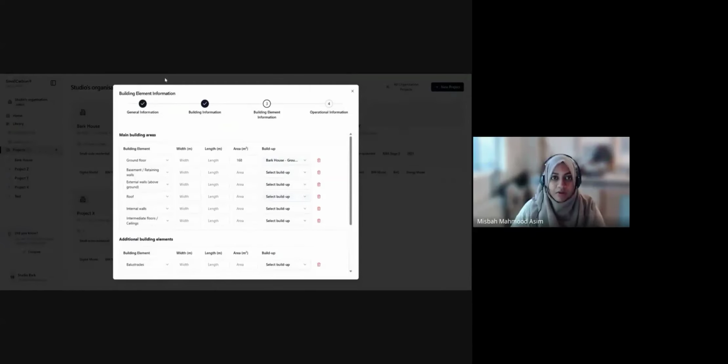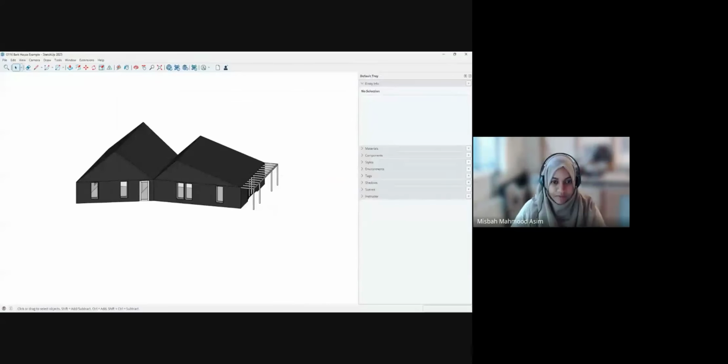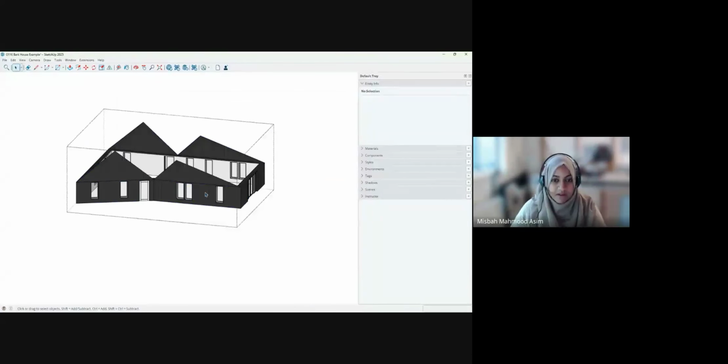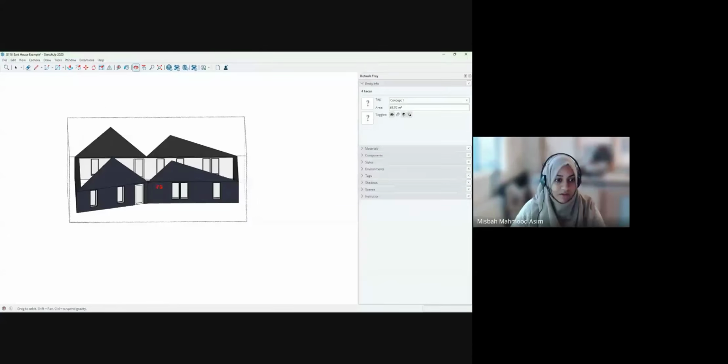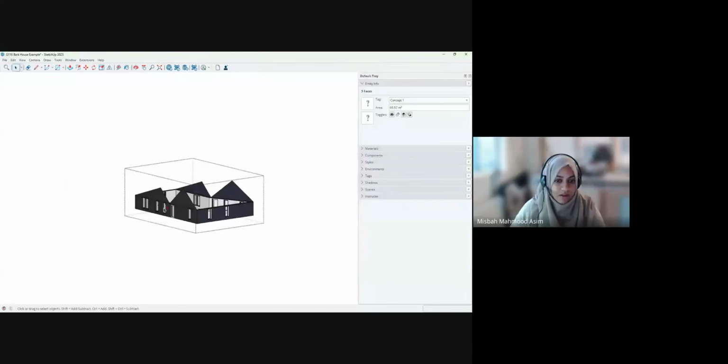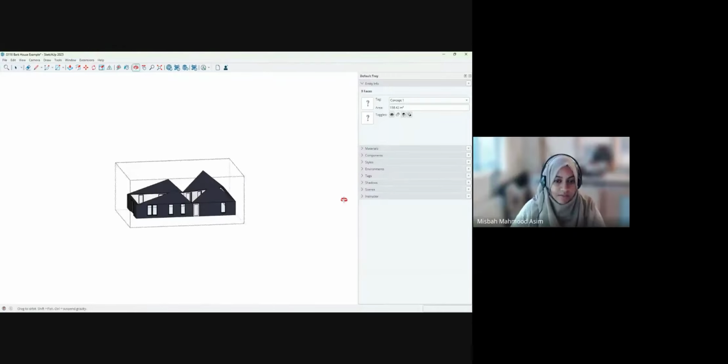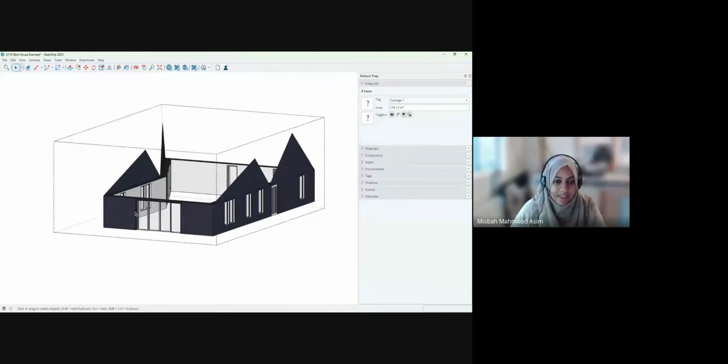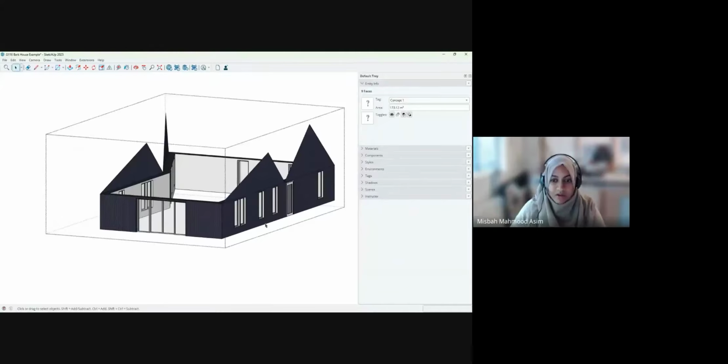But as an example of how this works with a digital model, I can show you one that I've made earlier. So if I was to take the areas of the external walls, I can simply pan over and select these areas, bearing in mind that it does not take into account the openings, so that would have to be within your area calculation.